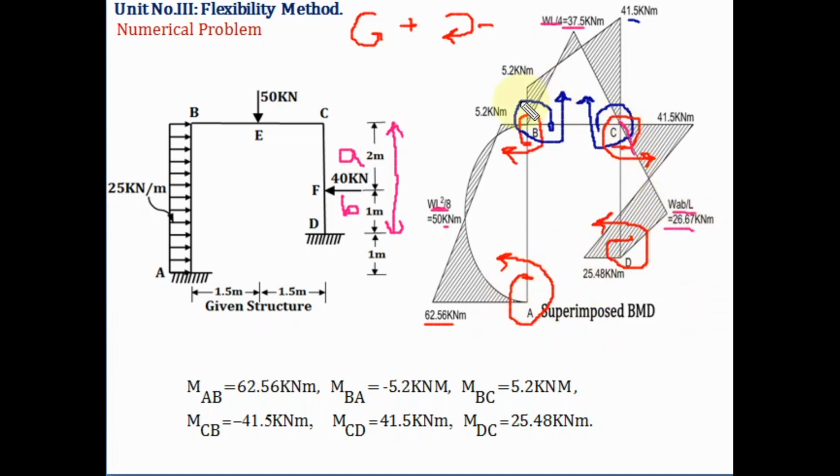So here we have superimposed the free bending moment diagram on the fixed bending moment diagram. So this diagram is a superimposed bending moment diagram. In the exam, if they tell you to draw the bending moment diagram, there you have to draw the superimposed bending moment diagram. Okay.